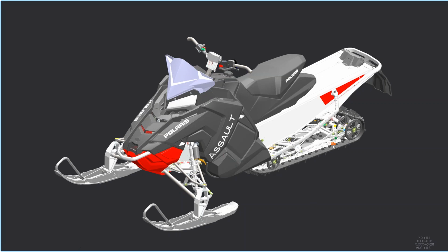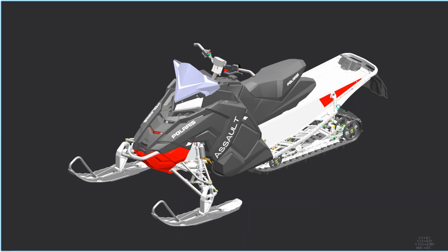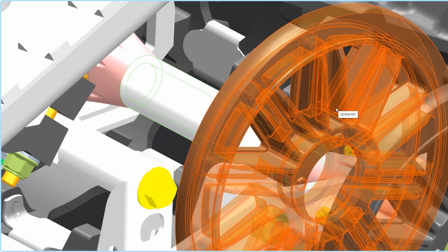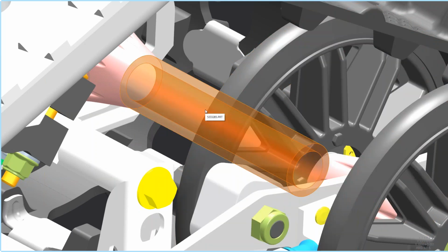And now let's say I want to pick up or inspect some features or some components in this lower chassis over here. Now, if I pick up that rod, let's say that I want to look at that a little bit closer. Instead of using my scroll wheel, I can quickly zoom into it if I use the zoom to selection command. And I can use this mini toolbar in the model tree as well. So let me pull up that model tree at the left.